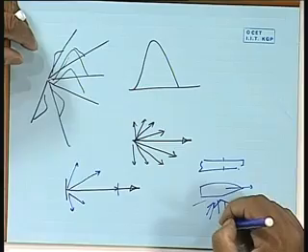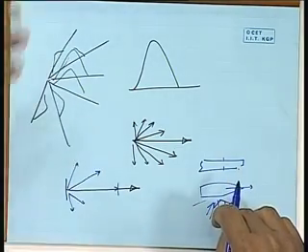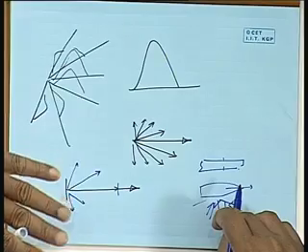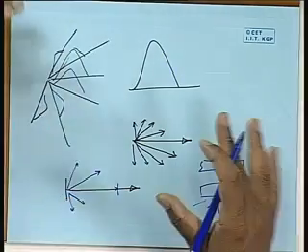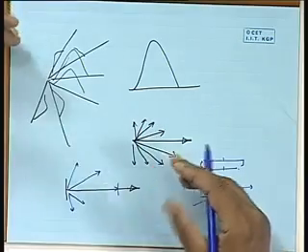For the clear case here, the roll, if you assumed all from one side, maybe it would roll say 30 degrees, but if you assumed it is spread, then it will probably be less. Of course, from the design point of view, what we still do is take long crested waves, because if I have designed the ship to withstand roll for all waves coming from one side, obviously if it is spread it will be less. So we are on the safer side. That is a different issue, but we should still know how we can calculate in short crested waves.